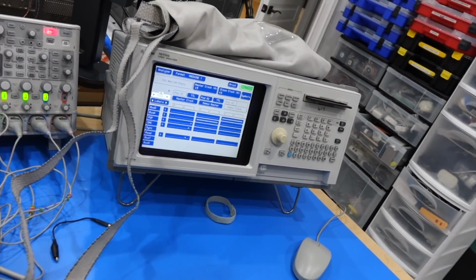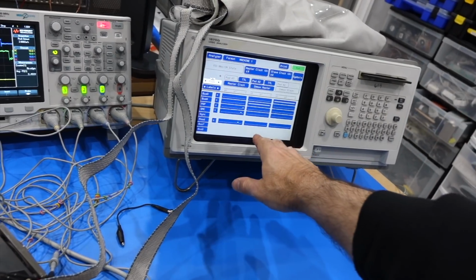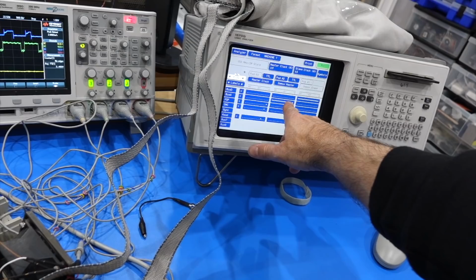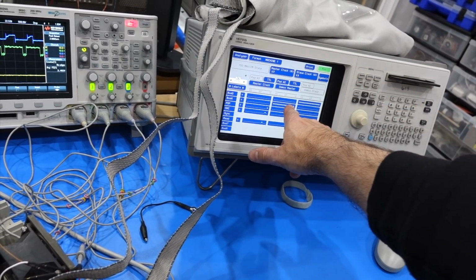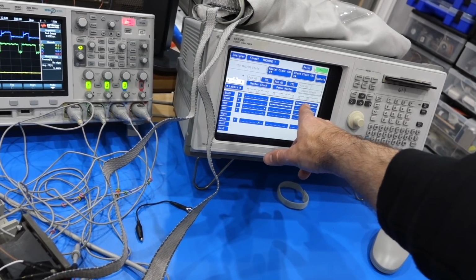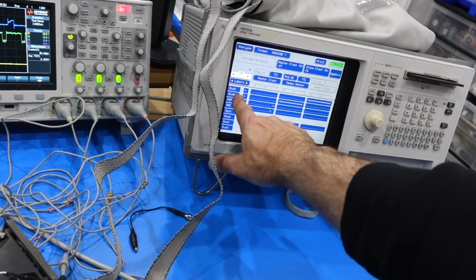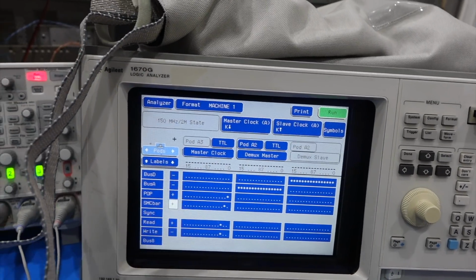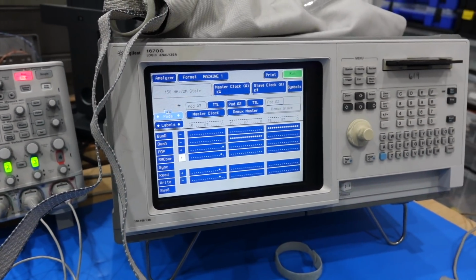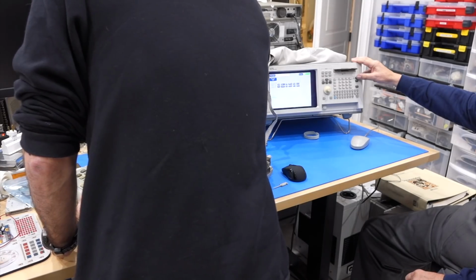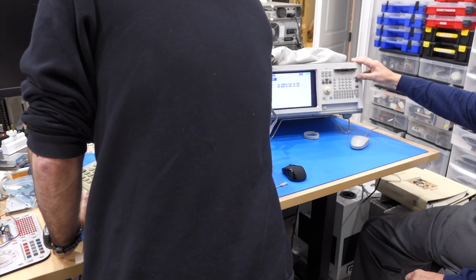Fortunately, our Logic Analyzer is clever enough that it should demultiplex the bus for us if we set it up properly. So address should be on the rising edge of STM, which is what you wanted, right? No, that's data. Right? No, you have it. You just have data and address inverted. Oh. And it's a negative logic bus, so we turn bus data and bus address. No. We'll see if that works. So reset this. I'm still hooked up here.